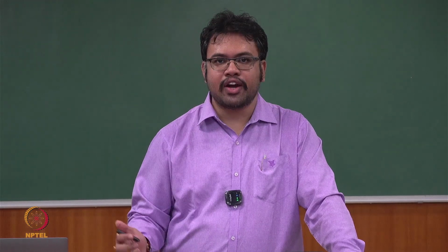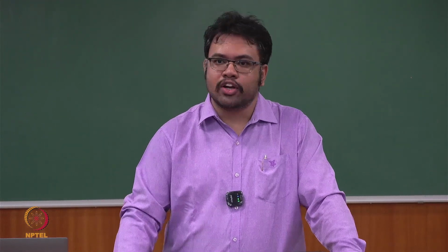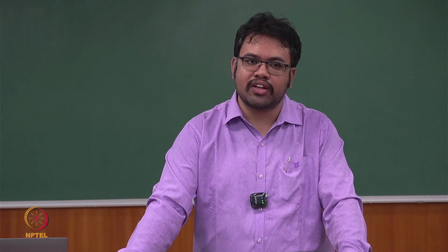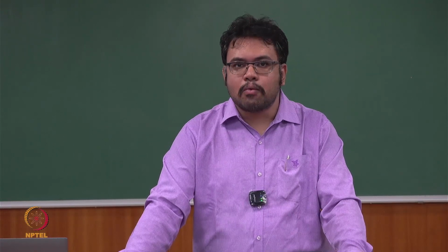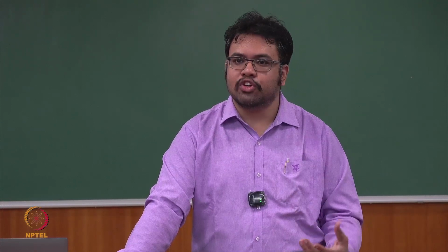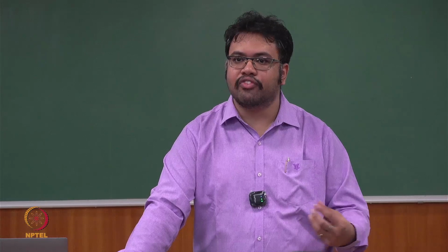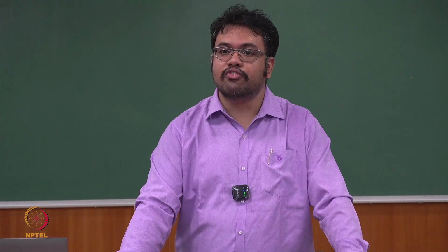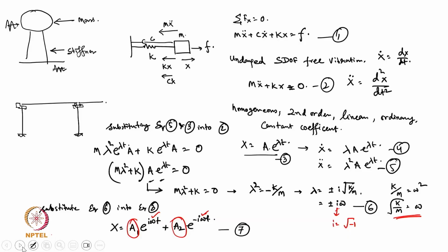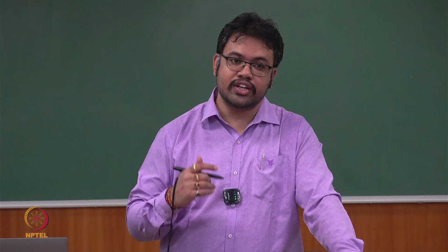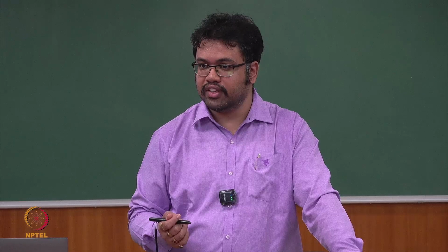After that, we made a simple mathematical model known as the single degree of freedom system. There we saw how we can idealize the mass, how we can take the stiffness, and what the first type of solution could be once we consider the system undamped and vibrating freely, meaning we are not applying any external forces on that structure. We saw how to formulate the differential equation, and how we solve each unknown coefficient from the initial conditions of that differential equation. Okay.